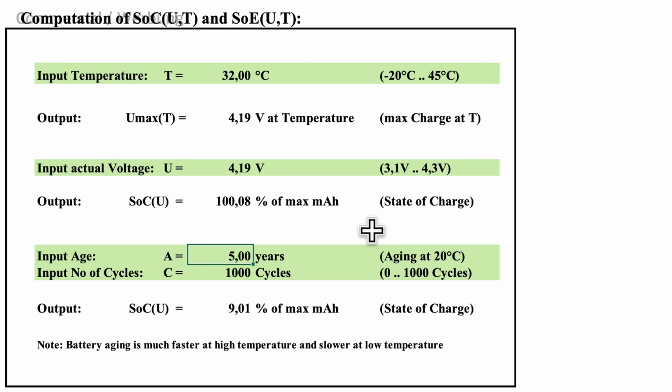Then we need to insert the battery age, which is 9 years, and the 327 charging cycles, which we got from the system report. Okay, now we get the state of charge relative to the original capacity of the battery after 9 years and after 327 cycles. Since the result corresponds to 100% charge at that time, it is equal to the remaining battery capacity. It is 63.5%.